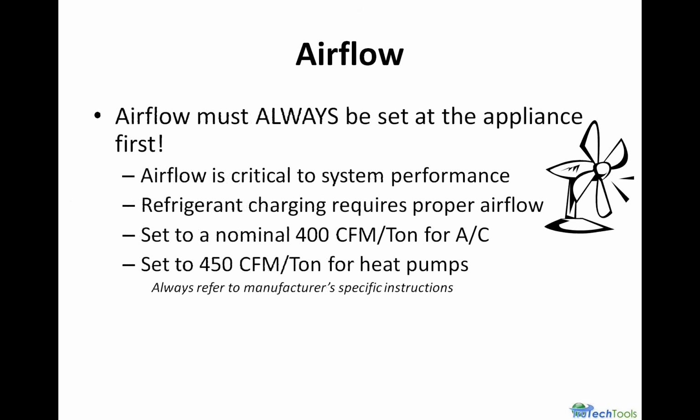Airflow always has to be set at the appliance first. So when we're benchmarking a system, we also want to make sure it's done first. Airflow is critical to system performance. Refrigerant charging requires proper airflow. Remember, you cannot get the charge correct until the airflow is correct. In fact, if you go out to a system, especially a fixed orifice system, and you adjust the airflow, you better check the charge. Because if you increase or decrease the airflow, you're going to change the way that system performs, and it could be undercharged or overcharged.